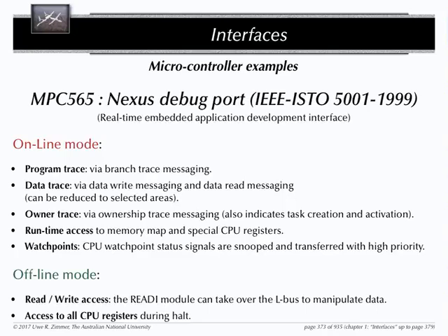Because it's not a real-time system. There's not really a need for that. You can just simply stop your machine and look at the registers in your own calm time. But in an embedded system, that's a bit different. You need to have this monitored on an online basis. So those kind of interfaces which give you live access to the current register values, and you can live change register values there, is a pretty important interface to have. Okay.